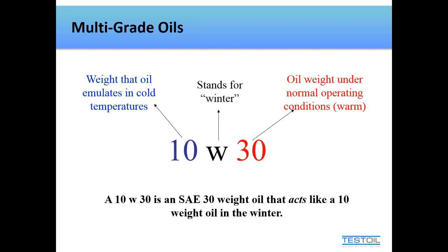Below 32 degrees, the oil changes its chemistry or its structure to actually allow flow during these really cold temperatures. You don't want to have honey in your sump at negative 20 degrees. You need something that's still going to stay pumpable when it's cold outside. So you want to get an oil, usually, say, a 5W30 or 10W30. A 5 is a little bit easier to pump during cold weather than a 10, which will be a little bit thicker during the cold weather. And it depends on the application, and what the manufacturer specifies that you should be using.